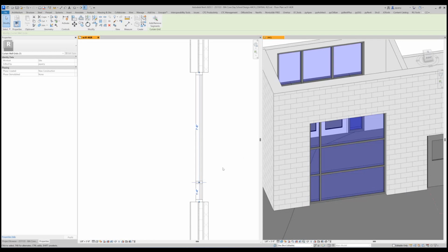Normally, you would see 2" whatever that distance is, 2" whatever that distance is, 2" and then the overall. Which is what ours will look like when we're done. It's not going to be 1'4" to the center, 3'1". Ours are going from inside mullion to inside mullion just to set the glazing size, because the other way makes the guy have to do math.